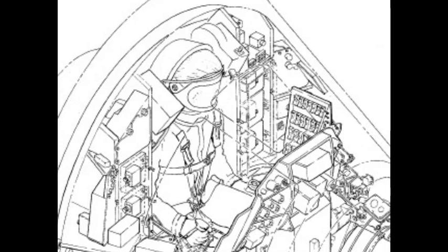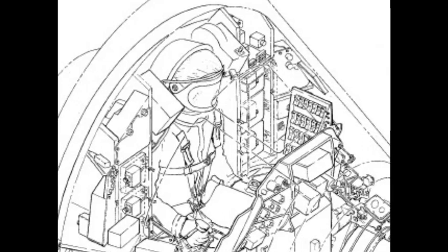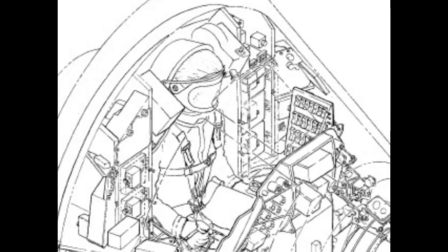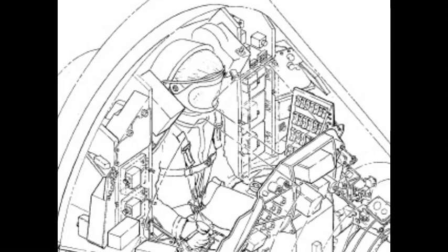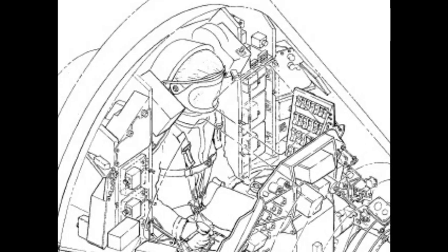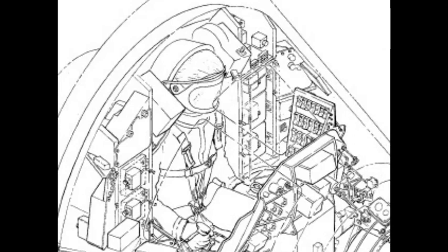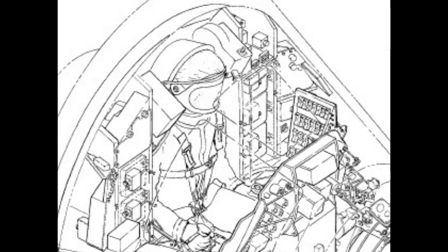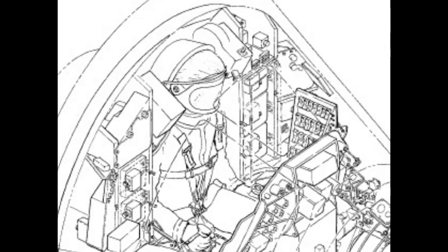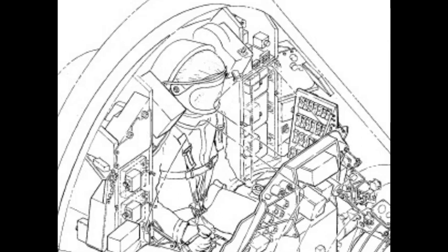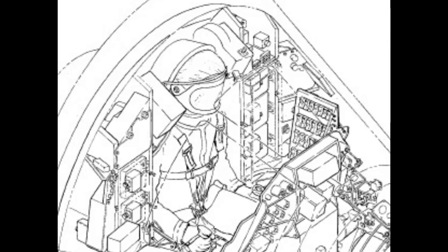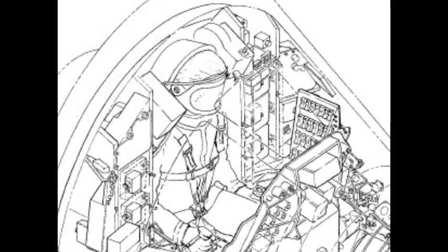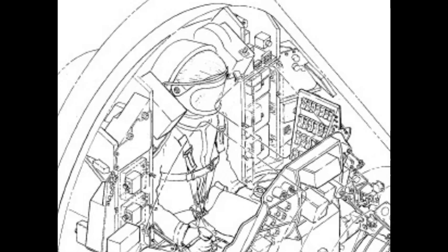2.13. Pylon. The capsule pylon, Figure 2.6, is a triangular-shaped structure that is designed to support an escape rocket and a jettison rocket. The pylon is constructed of 4130 tubular steel and is approximately 10 feet in length. The base of the pylon structural tubing is bolted to a steel flanged attach ring. A 4-foot escape rocket casing is bolted to the top, apex, of the pylon. Bolted to the bottom of the escape rocket casing is the jettison rocket.